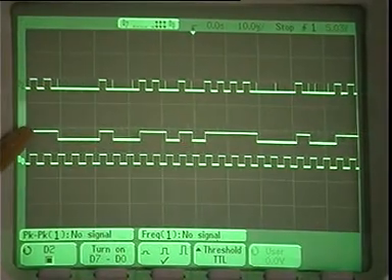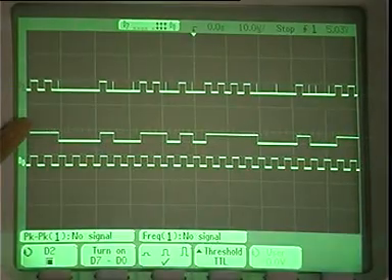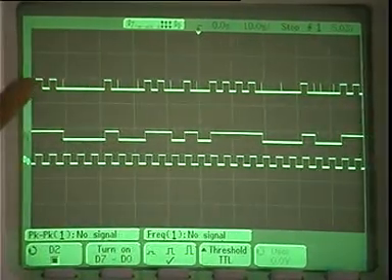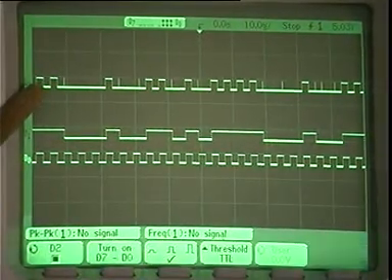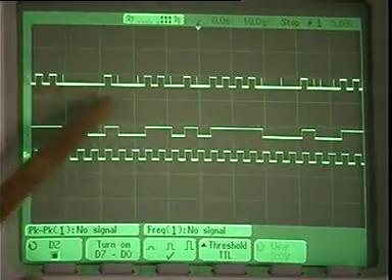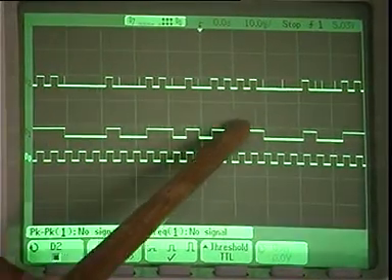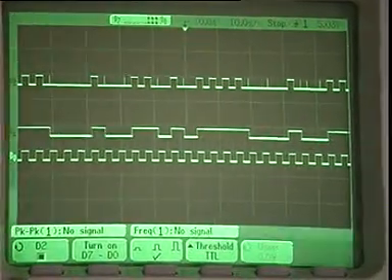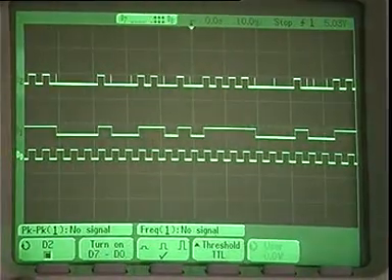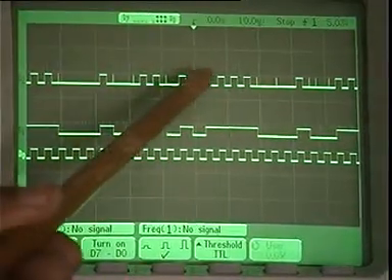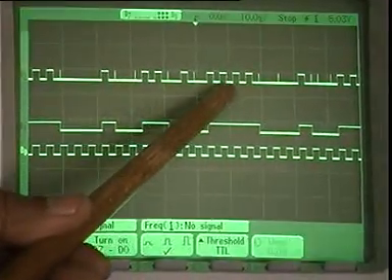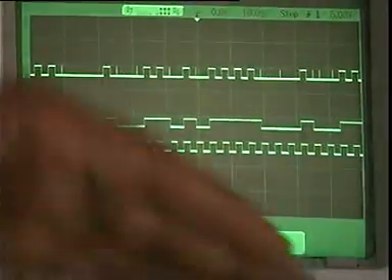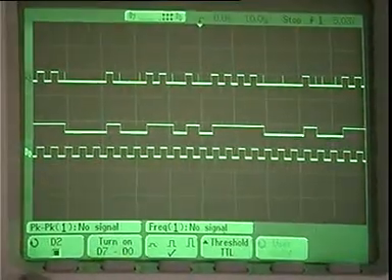There are 3 ones in this, and the corresponding RZ waveform is here. Let us take this one. There is a string of ones here, so there is a corresponding RZ waveform here. Notice that I occupy only half the bit period, and I come down to 0. Again occupy half the bit period, come down to 0, again occupy half the bit period, come down to 0, and so on. So this is how the RZ waveform would be transmitted.